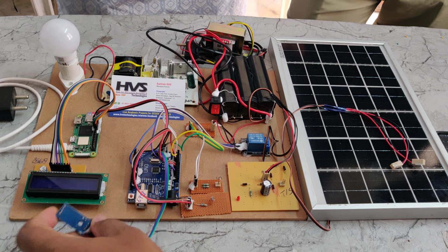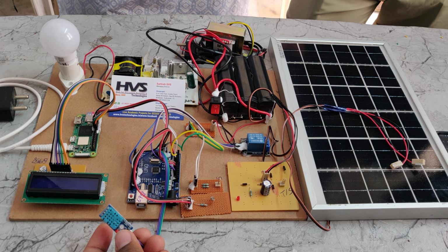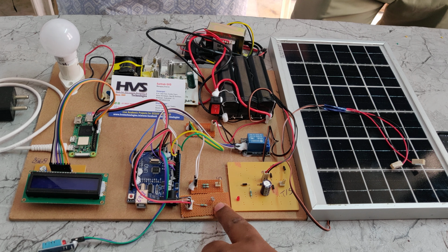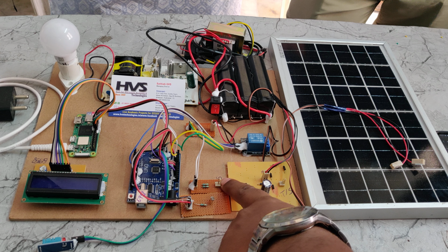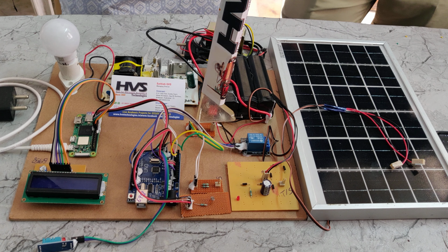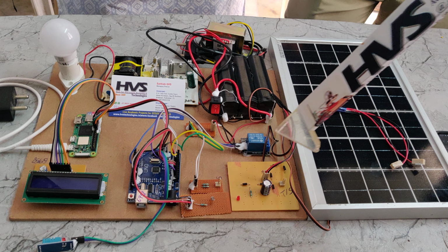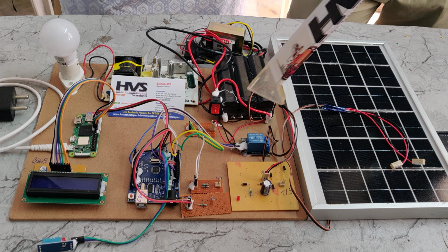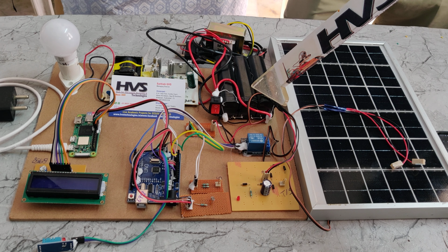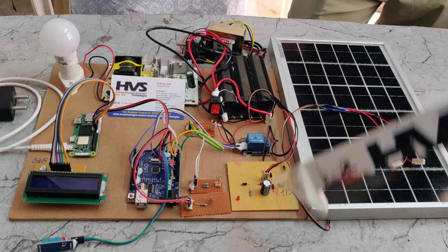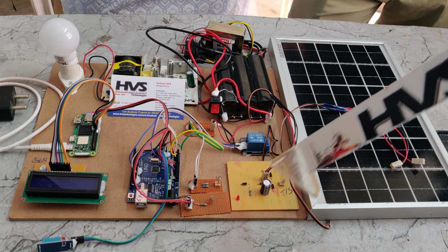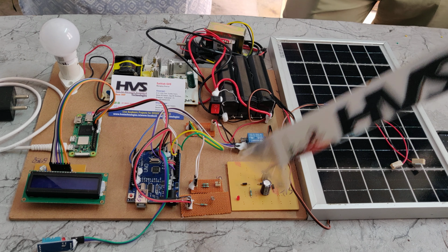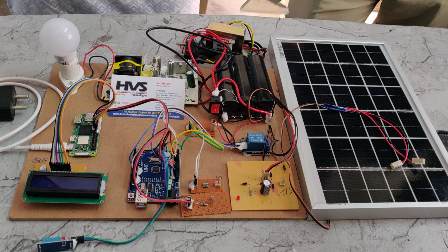The sensors we are using are the DHT11 to get the humidity and temperature, a light sensor, which is an LDR, this is the voltage sensor of the solar panel, and this is the voltage sensor of the battery pack. Next, this is an electromagnetic relay to control the voltages to the battery pack whenever the battery voltage is low. And this is the charging circuit, used to charge the battery pack with the help of the solar panel as well as from the grid.